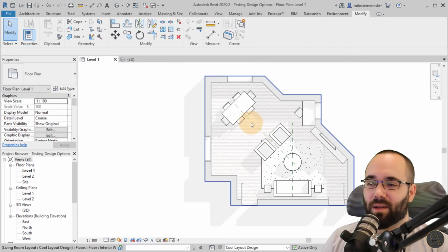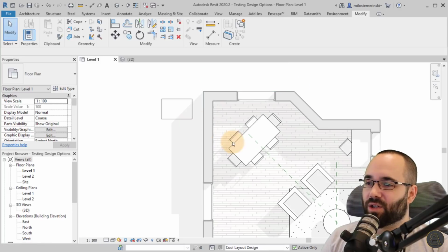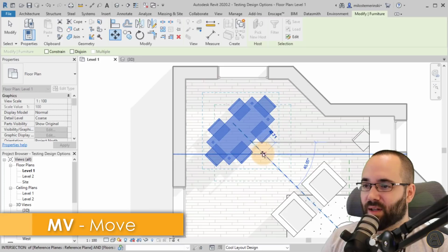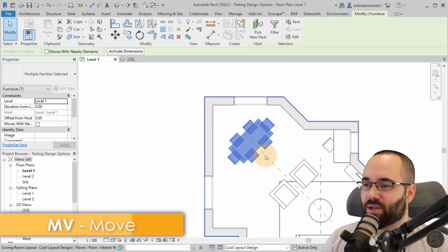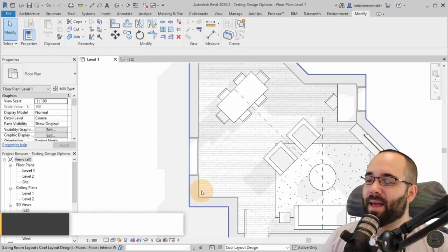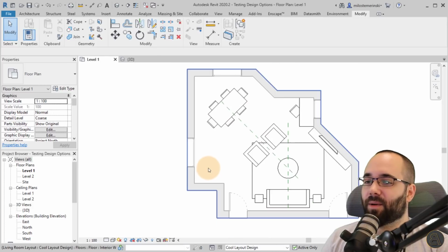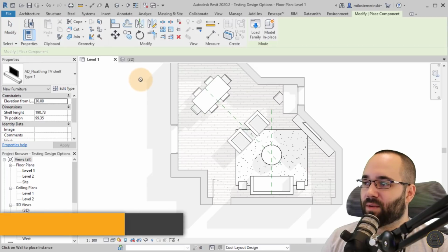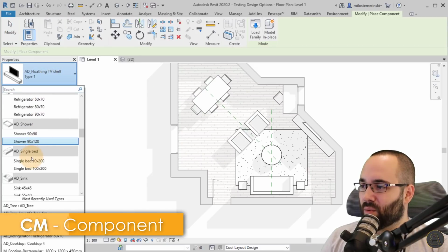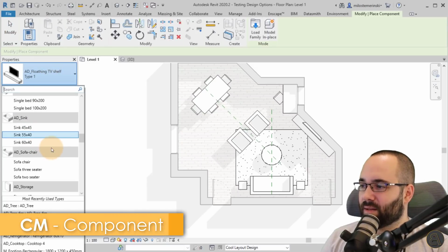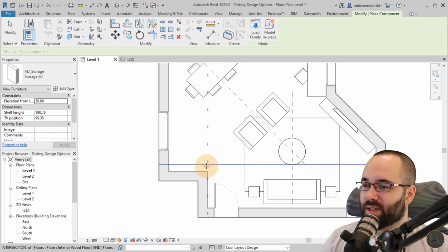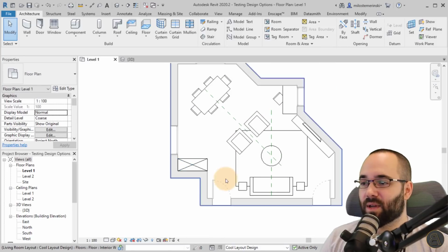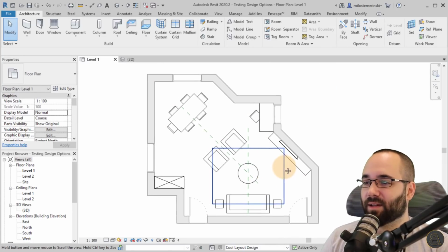See how the whole living room is now tilted? And actually when I see this table now, it might make more sense to move it a little bit closer in. Not too much, just a little bit. There we go. Add more room. And now here we have an empty area. So for that, I'm just going to add a little bit of storage. So go here to component, and I have these storage families. Let's see, storage 60 centimeters. I think that will do the job. Perfect. Yeah, so just have some extra storage in the house. I think it's definitely a good idea.